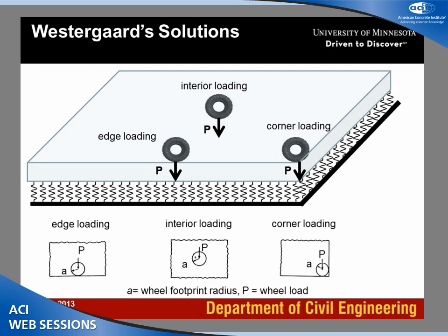Now, going back to material characterization, we had only a few parameters, mainly Young's modulus, but in this case it works in the opposite direction. If you increase Young's modulus, the stresses in the concrete slab will increase, but on the other hand, the deflections will decrease. So that creates two opposite trends, and it's much easier just to play with concrete strength if you want to prevent cracking, so increase concrete strength or increase concrete thickness.